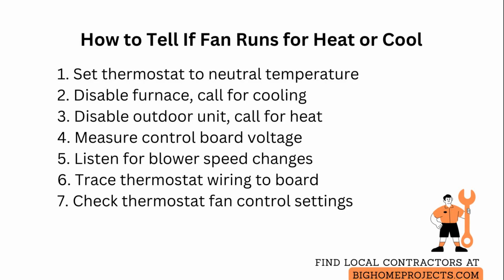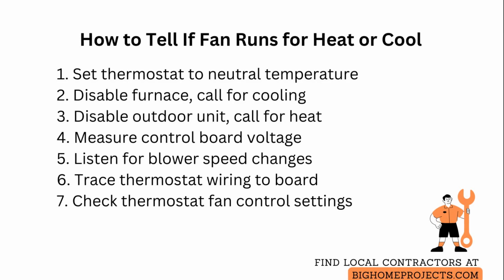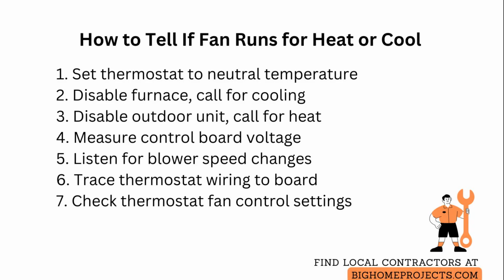Listen for changes in blower speed. Heating often uses a fixed set of speeds controlled by the furnace control board or a dedicated fan center, whereas cooling may ramp the fan with a loaded run capacitor and the air conditioner contactor. A distinct speed change when switching modes suggests separate control calls.